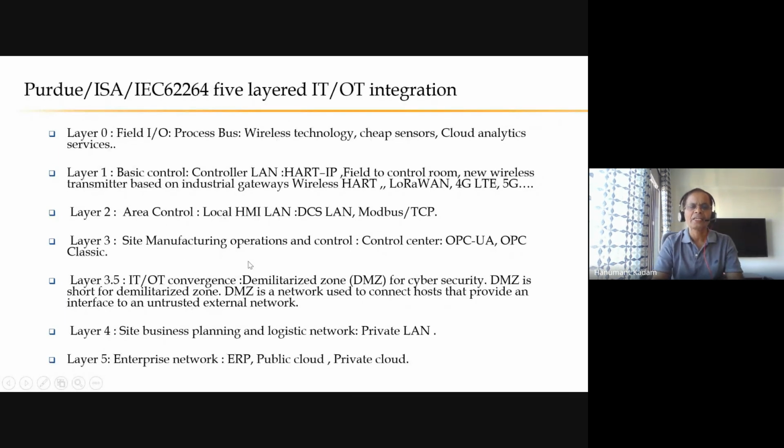Layer 3 is the site manufacturing operations, with OPC UA and OPC Classic. These are the protocols for sending data up to other applications, specialized software tools. And this is the layer 3.5 I was talking about. This is a security layer between IT and OT, IT/OT convergence. IT means information technology, OT means operational technology. So the demilitarized zone, DMZ, for cyber security.